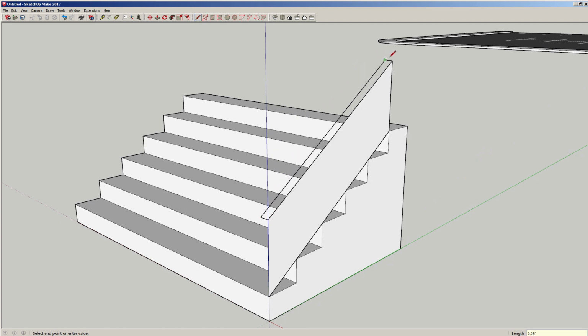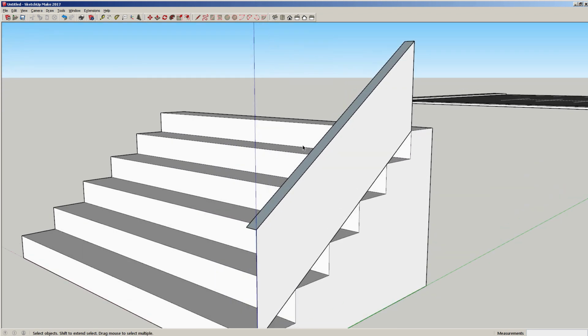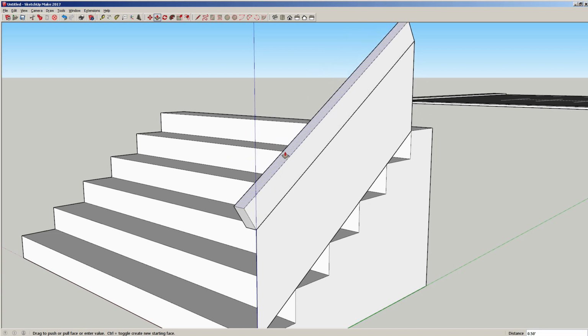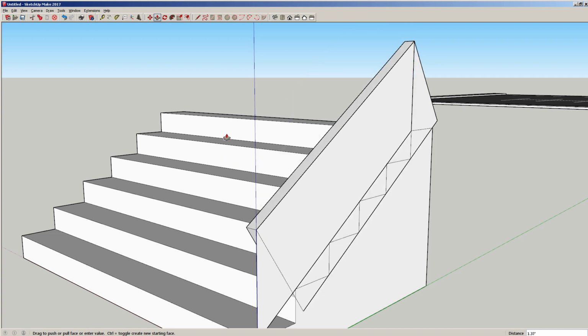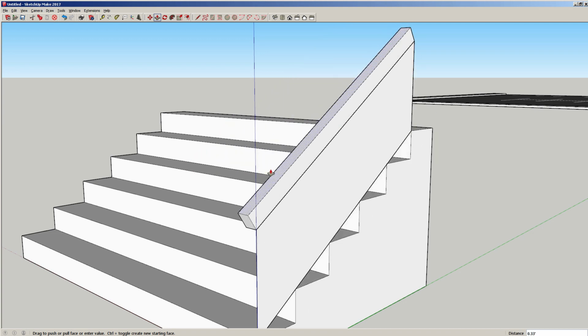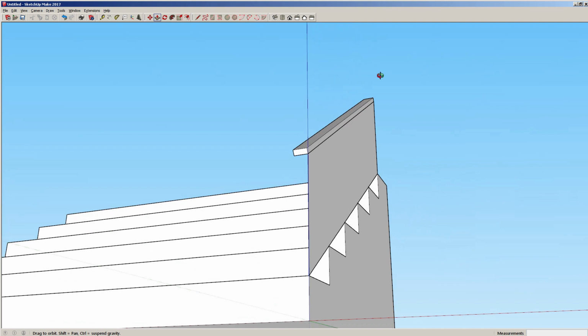Now we can connect these. And we just have to connect the last 2, because there's no line there because of the group. Right? Top of our rail. Press P. We're going to pull this up. No, I didn't press and release. So press and release and now it'll stick to your mouse. But it'll also try to match any background objects. It'll try to snap. We don't want that, so sometimes it's good just to keep it away from other objects if possible. And we're going to do 0.1. So there's the top of our rail.